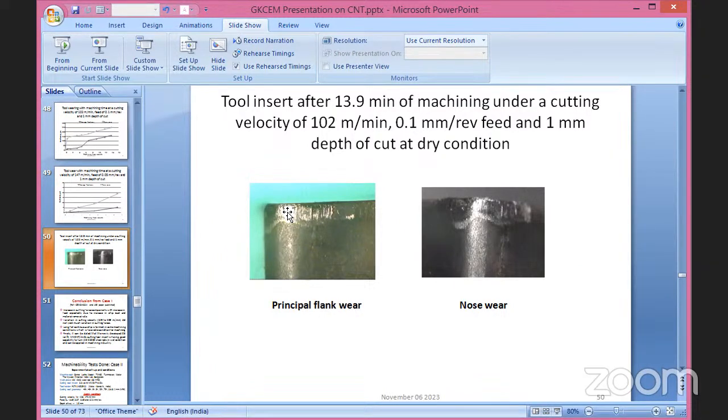Okay. So average flank wear is shown, and this value is somewhat low, obviously. If this value becomes 300 micron or more, then we should always replace this with a new one or grind it. But these are all ceramic cutting tools. These are in general non-grindable. These are all throw-away type of inserts. Okay.